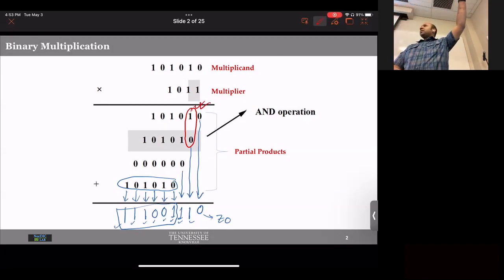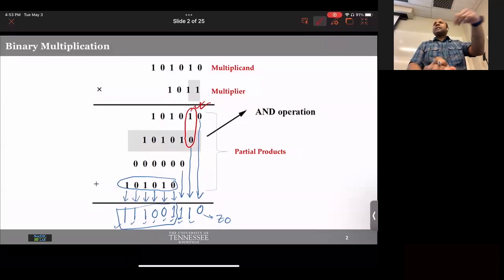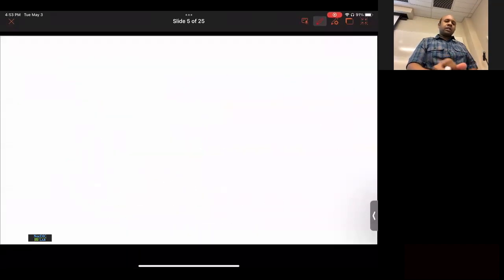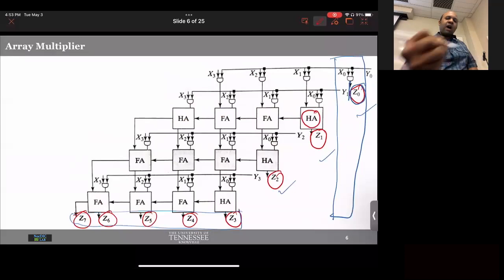Remember the half adder? We discussed this in the last lecture, that there are possibilities that you might not need any carry in at all, and you can simplify your circuit quite a lot by going for a half adder, which has 2 inputs. You completely ignore the carry in. And we can use a half adder for the second stage. That's what you see here. This is a half adder.